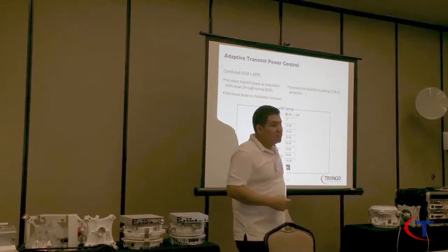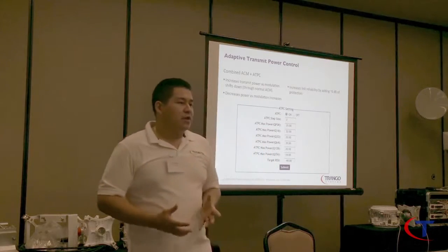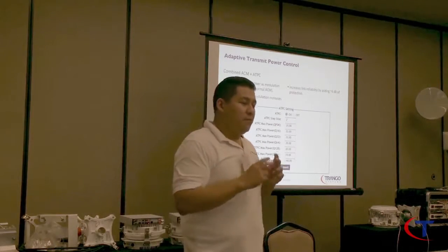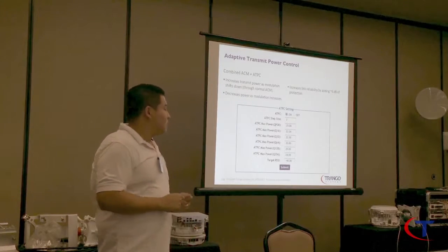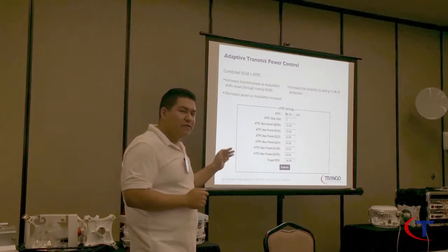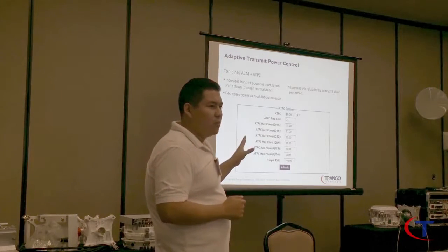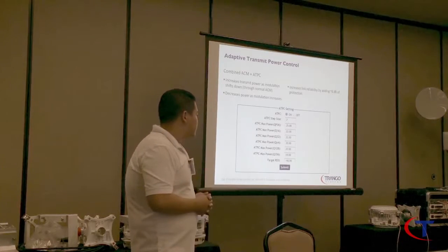Based on the data sheet of the product. If you buy an HP2, HP3, it's going to tell you right there what the max dBm transmit power is per modulation. I believe out of the factory, these are not set. They're all set at 15. I think that is the way they go out the door, unless you enable ATPC. I think we can configure them for you.